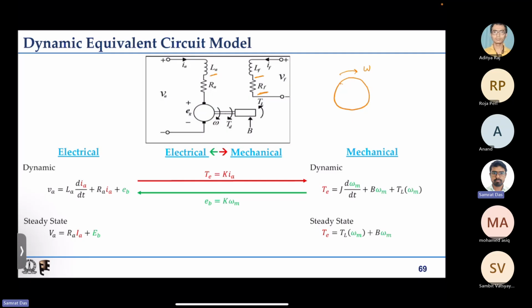That is similar to resistance in the case of an electrical system. So the frictional coefficient: if the frictional torque is simply put as b omega, then this is like a static thing. If you know omega at a given instant of time, you readily know what the frictional torque is at that instant. So on the mechanical side, frictional torque or frictional losses, whatever the coefficient is, that is a static element. But what is the dynamic element?